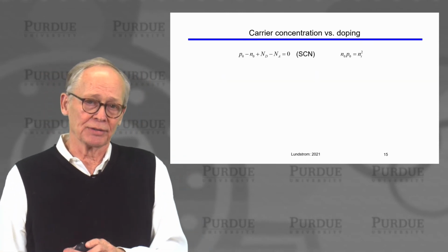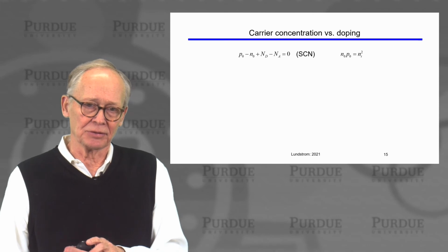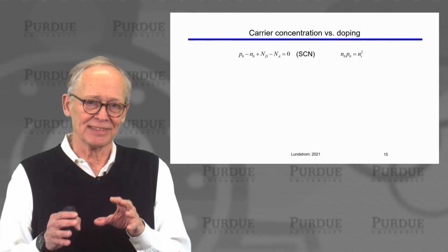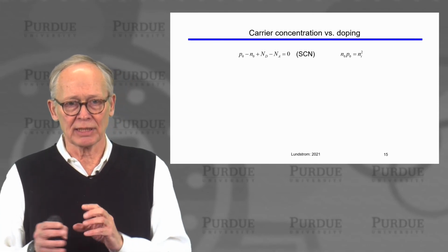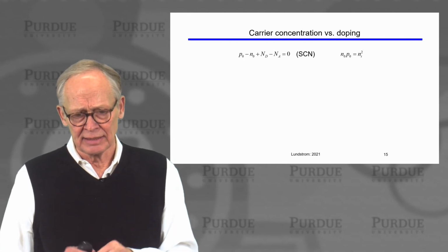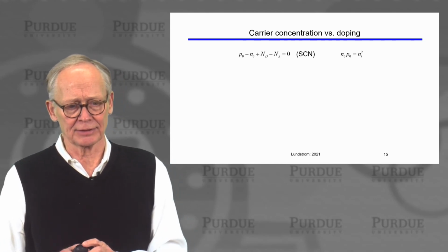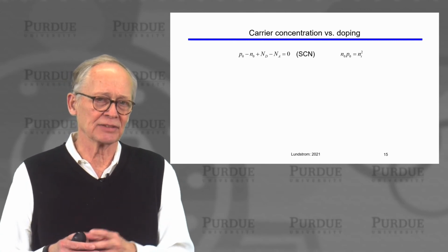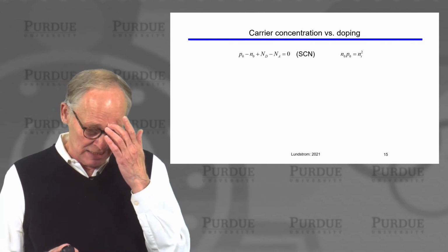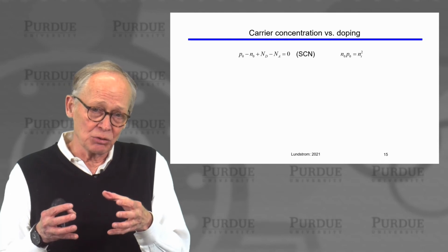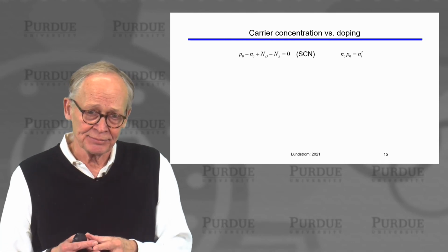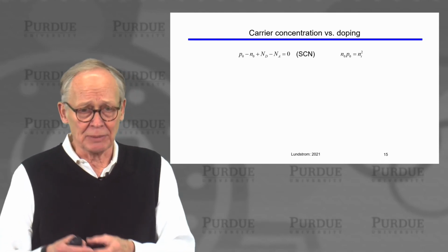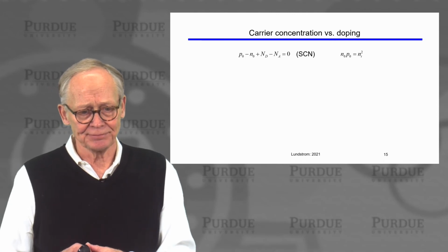Now, it was very important. What we're leading up to here is that the way we produce desired electron and hole concentrations in a semiconductor is largely by doping the semiconductor. And we talked about how we compute that, given a doping density. Well, we began by thinking that we have a uniform slab of semiconductor. We have n-type dopants, perhaps we have p-type dopants also.